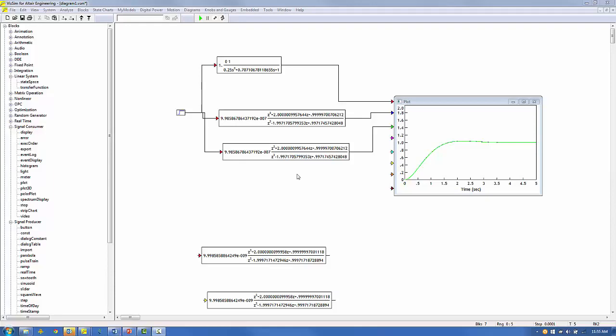Now we're ready to compare the percent CPU utilization of the discrete floating point filter and the discrete fixed point filter, both running on the Texas Instrument F28069M launchpad. To do this, we'll create a source model that will allow us to switch one filter on and the other off interactively. The input to both filters will be noise from analog-digital converter channel 0.